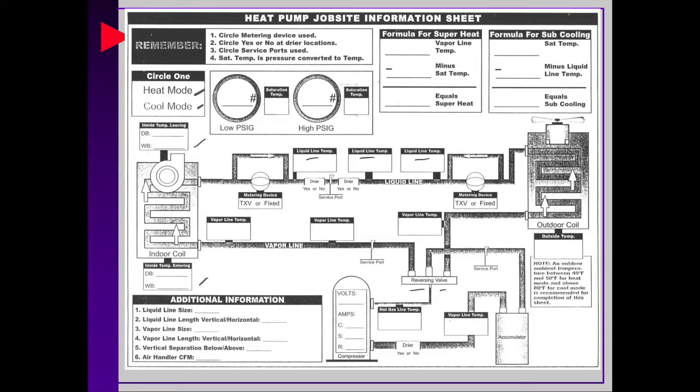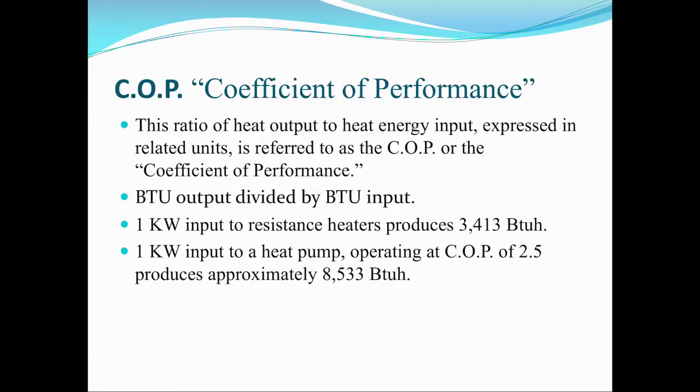What's the liquid line temperature prior to the coil? There's a lot of different details that they want to know so that we can identify if there's any particular problems with the system. And that's fairly typical in testing operation. And obviously, a lot of these we want to know: is it liquid, is it vapor, is it superheated, is it subcooled, giving us that capacity of what we're looking for.